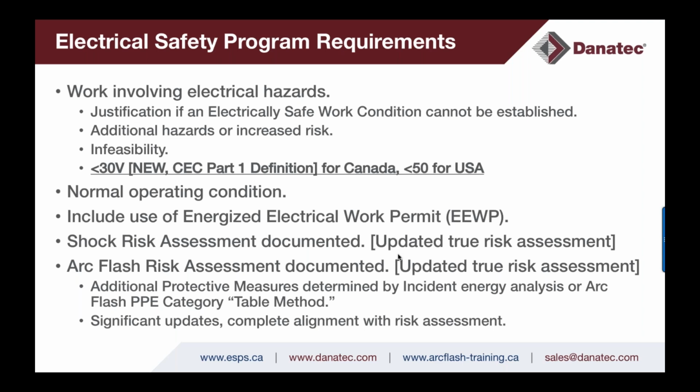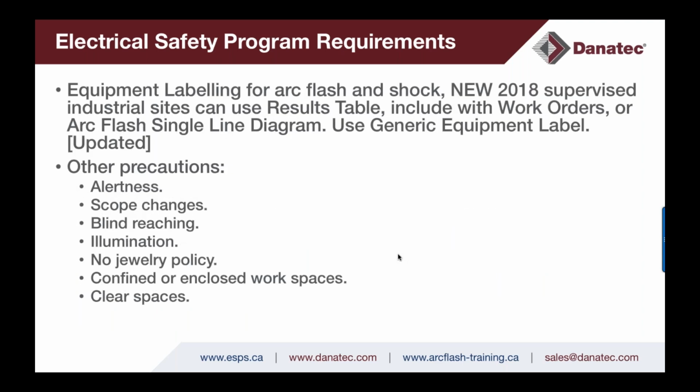The biggest change, in my opinion, was the electrical safety program beefing up its requirements and the risk assessment procedure, and then the arc flash risk assessment, and then the shock risk assessment. But under the arc flash risk assessment, that's where the significant changes are, and it's a completely different process than probably what you're implementing or what you've been trained on previously based on the 2015 edition training. So significant updates here, and these 2 individual risk assessments are now completely aligned with what would be called risk assessments in reality. So more discussion there, and I'll cover that in the part 2 webinar to be scheduled.